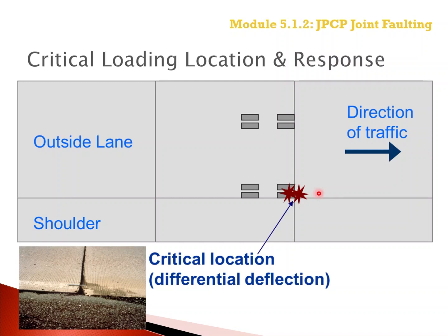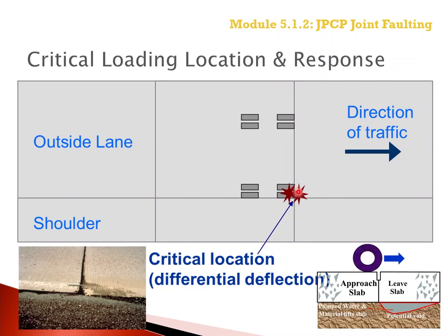Each of the axle loads is moved adjacent to the transverse joint for calculating the deflections to predict the faulting resulting from each axle configuration, including single, tandem, tridem, and quad axles. In summary, or as an overview, the axle or wheel loads are placed at or near the corner of the slab.